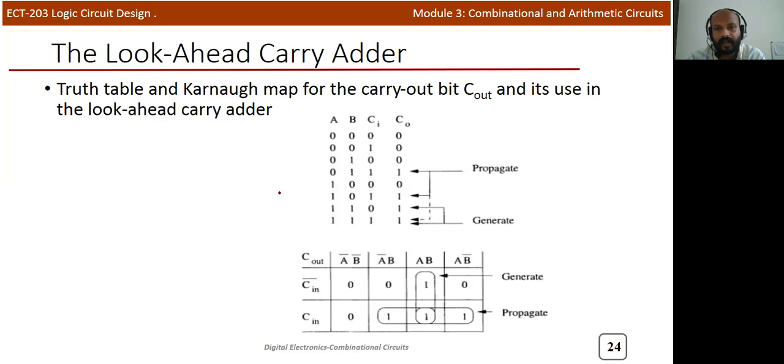And I already explained that by using a K-map also I can conclude the carry generate and propagate logic. This is the same two tables we defined in the previous slide. So from this particular example you can see that the carry generate logic is indicated and grouped here. This is simply AB. So that's why we indicated carry generation logic G is equal to AB, and this logic is carry propagate. If you write the truth table and the Boolean expression for this, you can see that